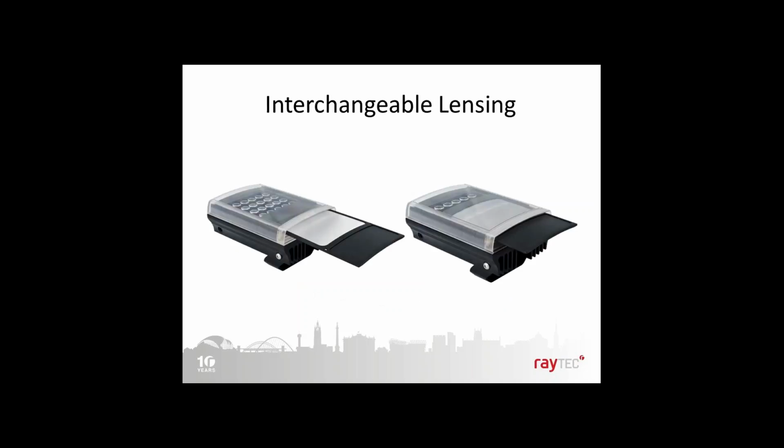The interchangeable lenses basically allow you to change the spread of light. I spoke before about the spread of light compared to the angle of the lens of the camera. So this allows you to change the spread of light very quickly on scene. With a lot of other illuminators on the market, if you pick your illuminator, you are set at a fixed angle, and there's nothing you can do once you've purchased that. If it's too narrow, you've got to send it back and get a new one, or if the camera scene changes or something happens, then you're stuck with the angle of illumination. With Vario, you can slide the lens in and out very easily, and this lens technology has been designed to help the camera.